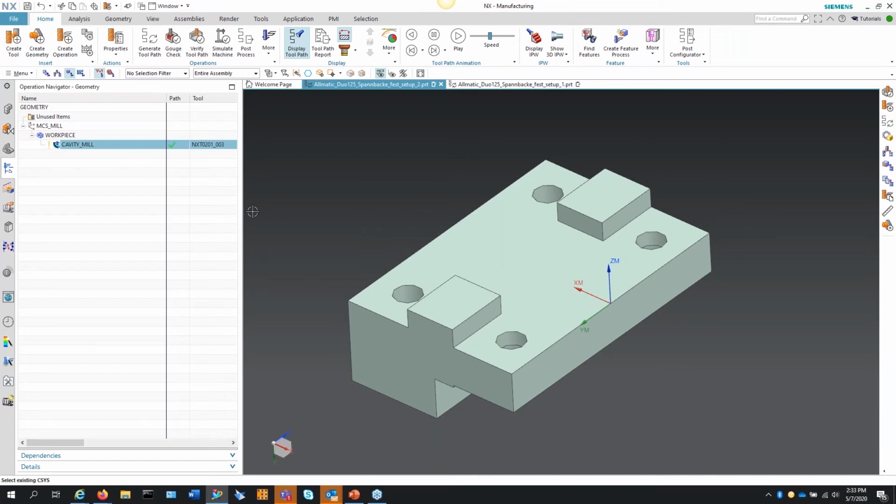NX has those utilities as well to put patches over top of holes or grooves, because if the tool can go into that area, it will try to go into it. And when you're running 75 inches a minute, you don't want any interaction of different axes or letting your ball screws reverse. You'll see it on the part every time. Even on brand new machines, the backlash is always there.